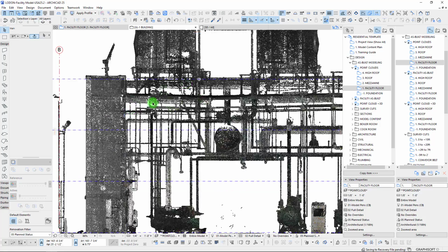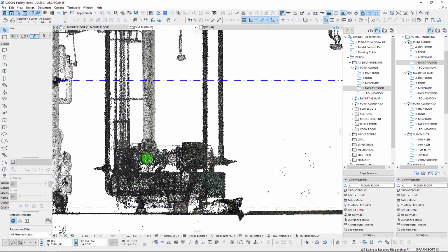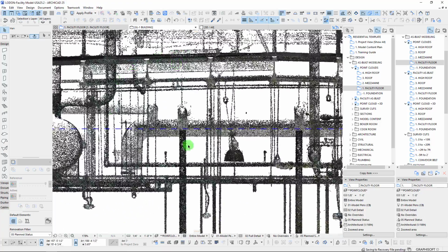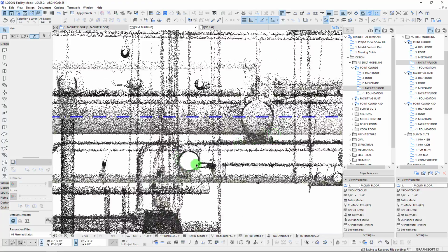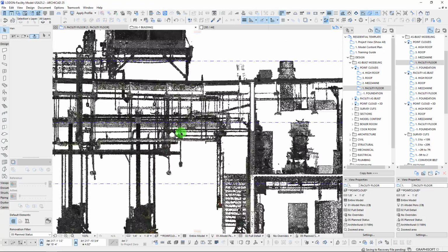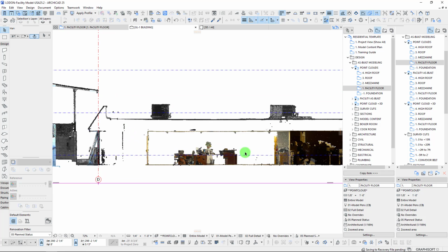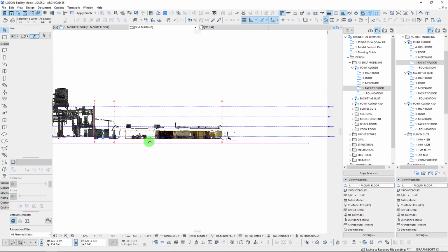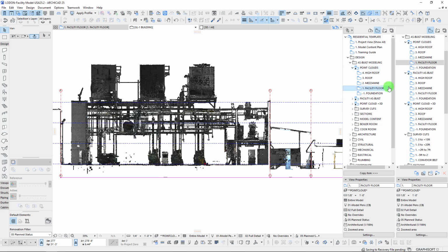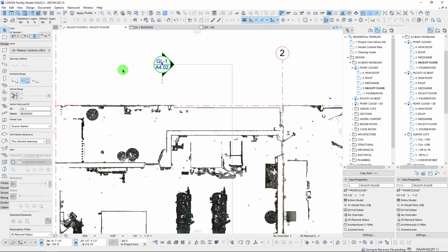So this is just the point cloud, and you can see that cut there through that engine room, which is pretty nice. I mean, this is how you start modeling these complicated overhead systems: do a survey, and then it makes it really easy to locate those in elevation there. You can see here that we're cutting over, and our office space there is a few feet lower actually. So that would be a section here. Let's jump back to this floor plan view.